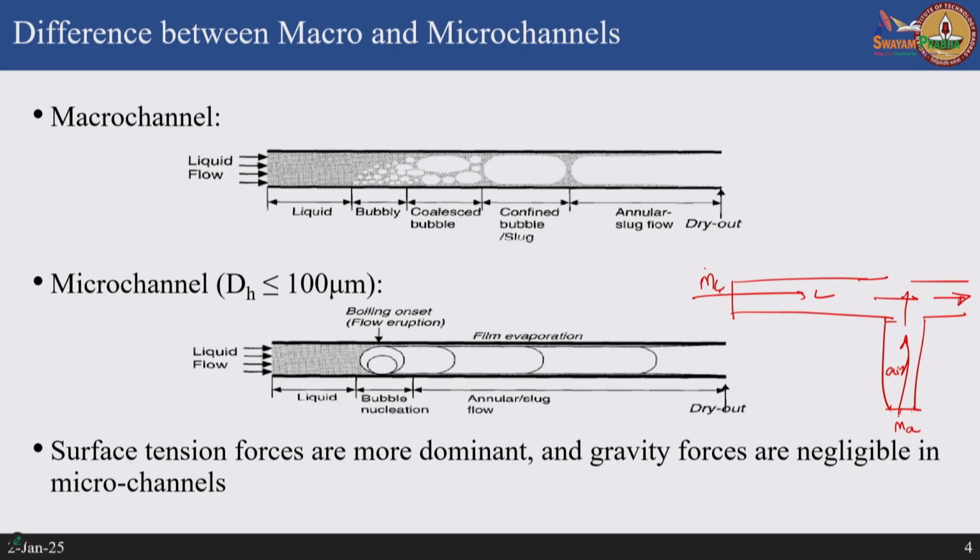Accordingly, I can produce different types of two phase flow patterns in these tubes. So, that is one way, that is basically an isothermal two phase flow pattern that you can observe when there is no heat transfer, but you just change the relative mass fraction of the air and the liquid that you mix in a T junction, and then you observe how the different flow patterns look.